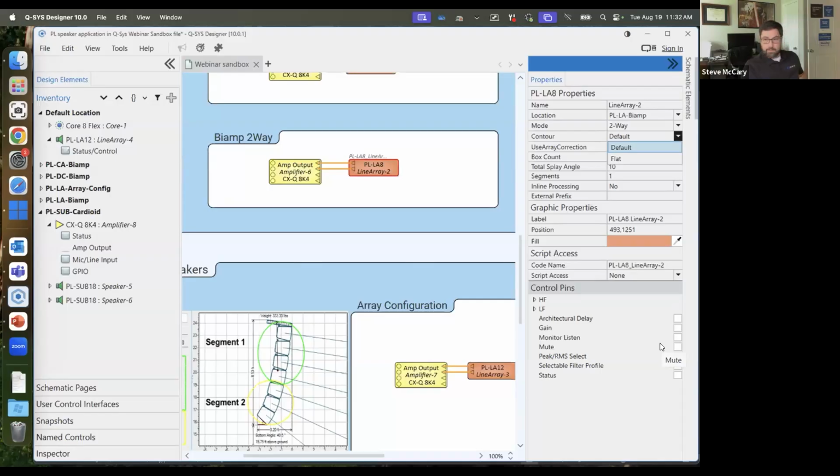They're all stainless screws and ABS enclosure, all that stuff. At least the LAs are all ABS. The hardware is stainless, which again is covered by another ABS cover. Fly frames are aluminum, and then the DC and CA boxes are weatherized plywood with a Duracoat on the exterior. All grills have a stainless mesh right behind the grill so that water ingress or dust is pretty much controlled. So they are usable in what we consider outdoor protected areas.